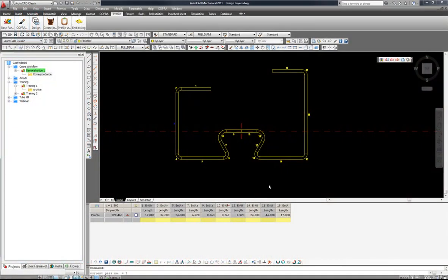In this next section, we'll be looking at unfolding our profile with the new parametric spreadsheet functionality, which we can see here docked in the bottom of our AutoCAD interface. Previously in COPRA, this was in a separate window and information would need to be manually transferred. We now have direct and real-time possibilities. In other words, when we type in new angles, new station numbers, they are automatically and immediately added to the spreadsheet.